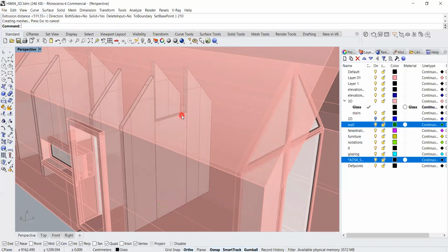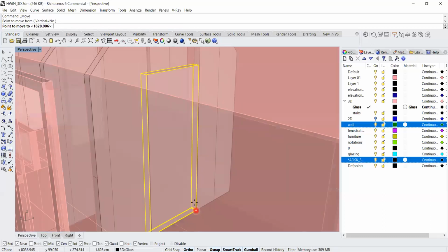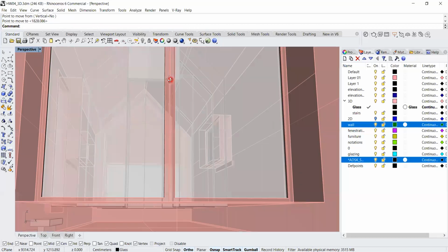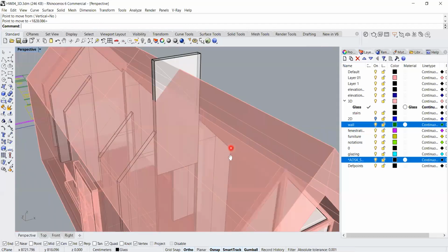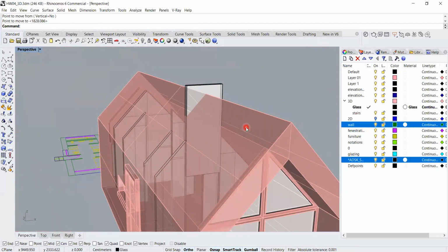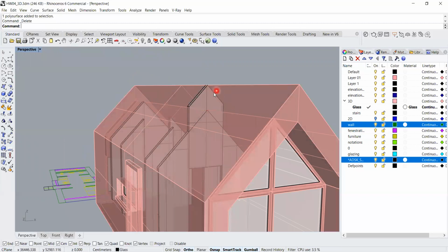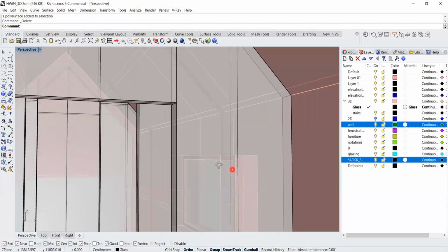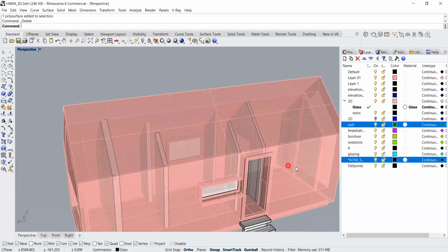And then you have this one, so I select this one and move it 210 centimeter up, so it becomes something like this. So it becomes like a door here, okay? And then you can do that split thing again here. So you can Boolean split, okay, this and this one, okay? So you can then easily delete these two parts. So you have the inside parts as well. So it becomes the door. So everything can easily be done with Boolean split.